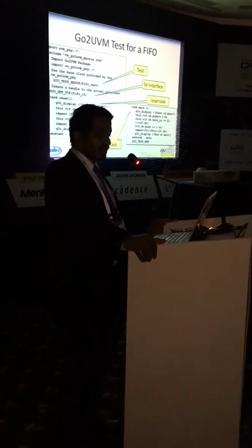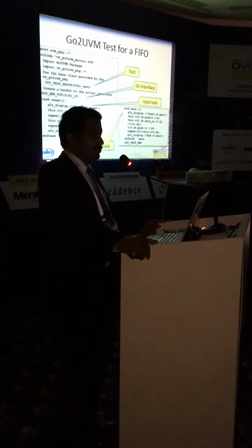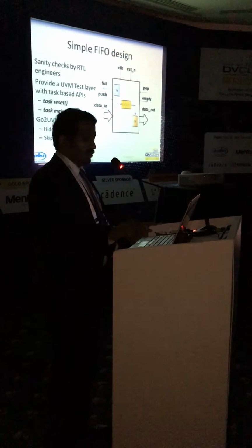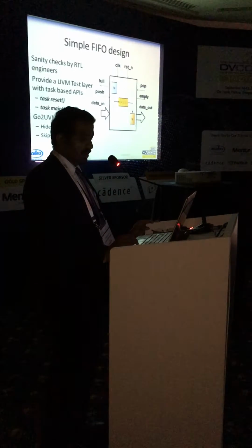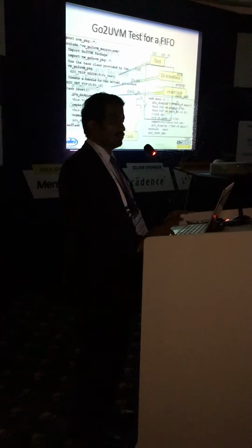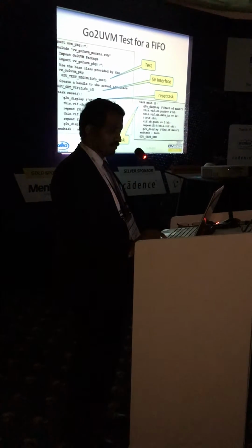Reset_n to be 1 towards the end of the reset task. Let's come to the main task. In the task main, we just have a main display, and then we go and say, okay, let's push. Again, please remember it's a FIFO design. Okay, you can do a push and then send some data and then get out. If that's all a designer wants to do, this is all he or she has to do. It's that simple. We get it up and running in about 5 minutes with UVM.